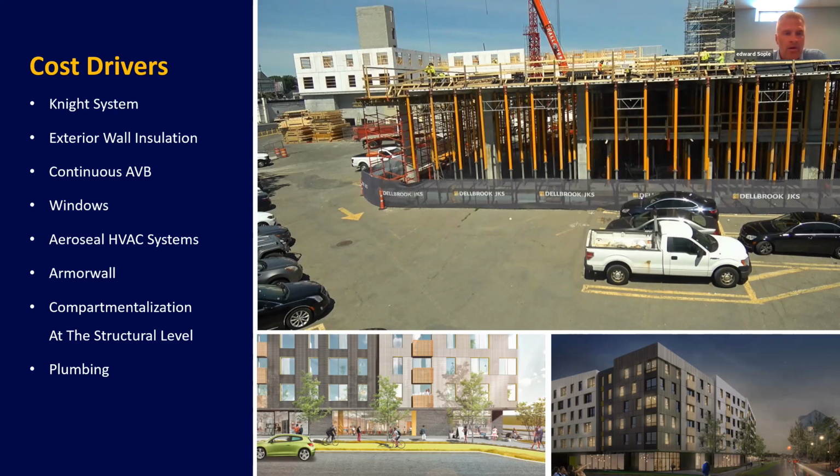So Armadillo wall is an interesting one that I learned. That's thermal bridging. Anytime you have a Juliet balcony, or a canopy, or anything that extrudes out and needs structural support outside of the sheathing, you need a continuous air barrier, but you also need the structural component to attach to your building. They're called structural blocks. It's minimal cost, but it's definitely another driver.